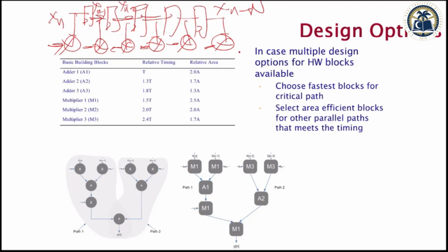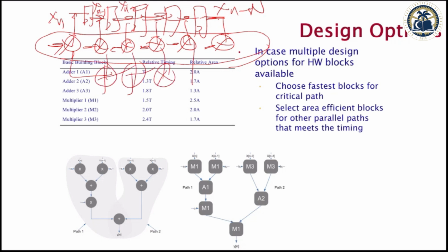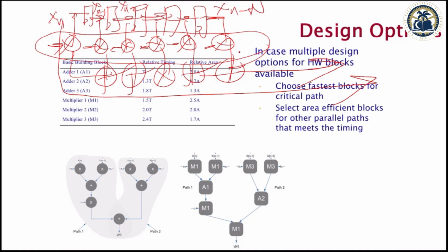But these registers, if you look at one register to another, to another, is not adding any value for breaking your combinational cloud into pieces, because you have a big combinational cloud, which is this one. It has to do the multiplication, then addition, then addition, then addition, and finally the predicted output. So this path becomes a critical path. One multiplication and so many additions. And after that, you can take a new value. If you take it before that, you are going to get wrong answers. So you've got to make your circuit fast enough.